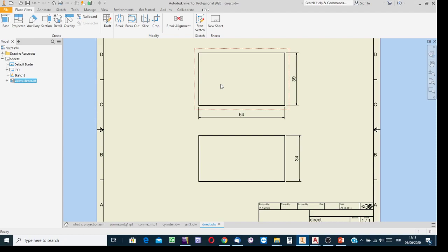It is a rectangle. What is the projection in shape on the top side view? It is a rectangle. So the front view is a rectangle, the top view is a rectangle. From your experience and studying in the writing part, if you create the views of a rectangular prism, you obtain two rectangles, top and front.